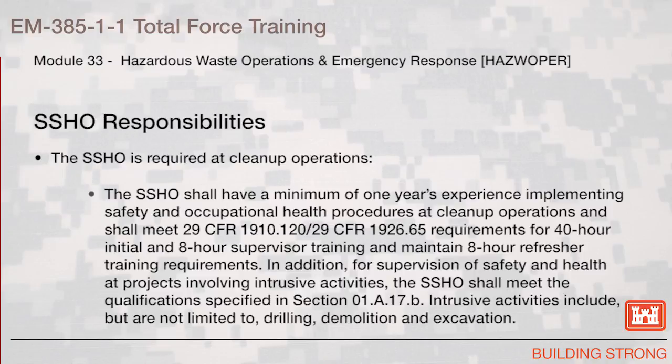SSHO responsibilities. The SSHO is required at cleanup operations. The SSHO shall have a minimum of 1 year of experience implementing safety and occupational health procedures at cleanup operations and shall meet 29 CFR 1910.120 or 29 CFR 1926.65 requirements for 40-hour initial and 8-hour supervisory training, and maintain 8-hour refresher training requirements.